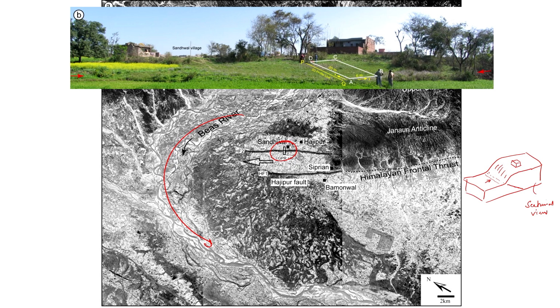Now, the concern was that there is a pipeline which also goes through here, and the arrows which have been marked are the probable location of the fault trace, with an understanding and experience that this is the scarp and the fault plane must be over there. So, we did GPR over here, and that helped us in identifying the particular site. This was like, topographic profile also you take and all that.